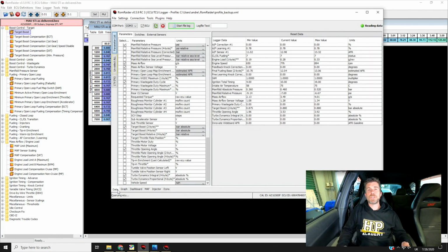At this point, we're going to assume that we've created a log file. So we now want to figure out how to interpret that. Now, actually, before we do that, also just worth mentioning how to drive the car while you are gathering your data, because when we are performing any tuning based on data log information, it really comes into a situation where garbage in results in garbage out. So we want good quality, clean data to give us the best chance possible of getting good results.